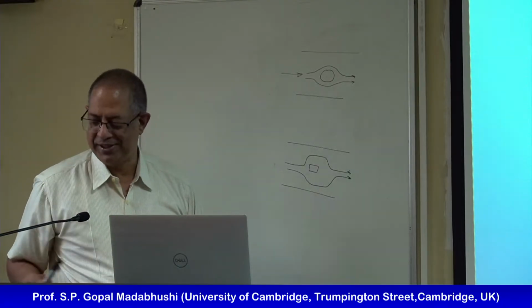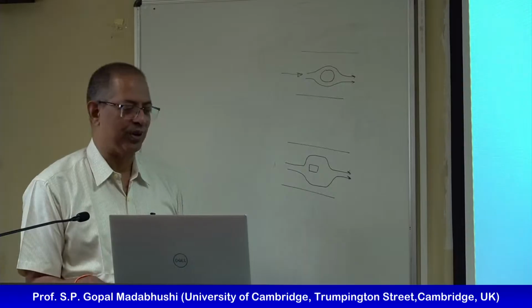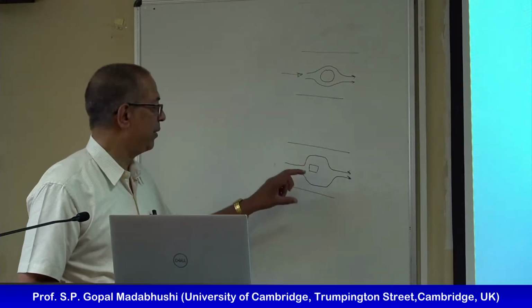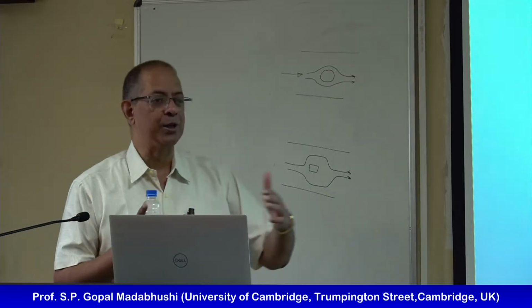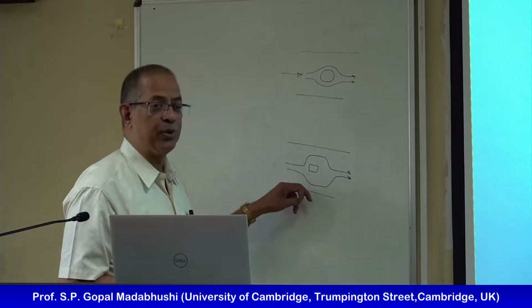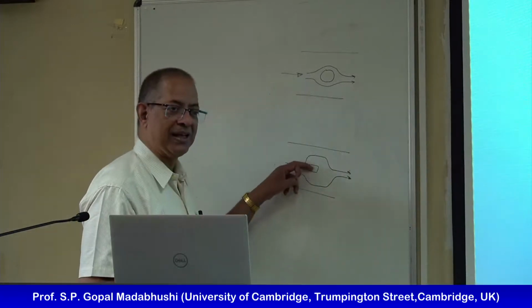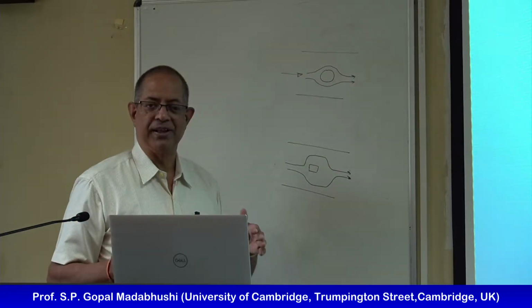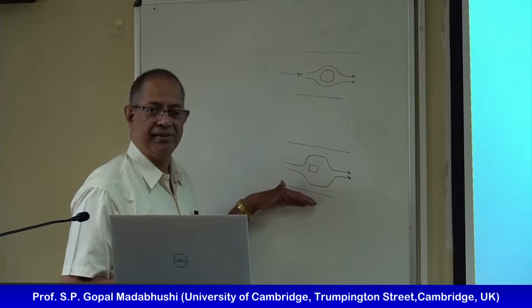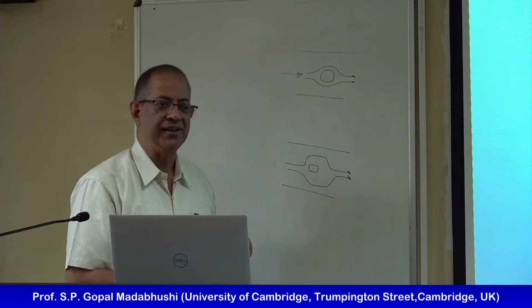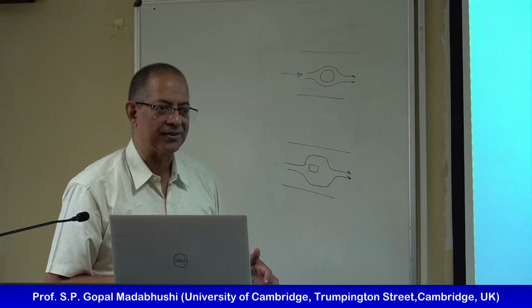At that point, my thought was, really this is going to make a big difference when you have multiple piles, right? If I have a lot of piles, then depending on pile spacing, this zone will overlap with the pile in the next direction, and therefore the soil will have to make even more deviation and it can't flow in between the piles.